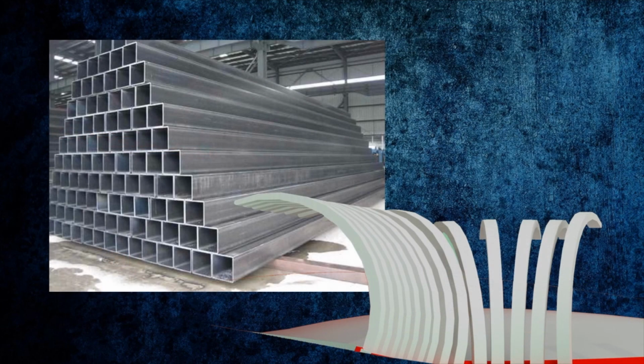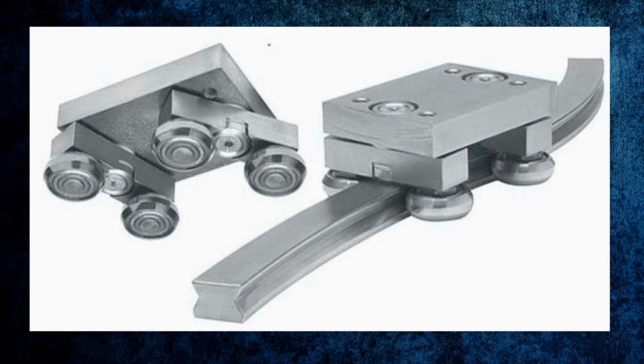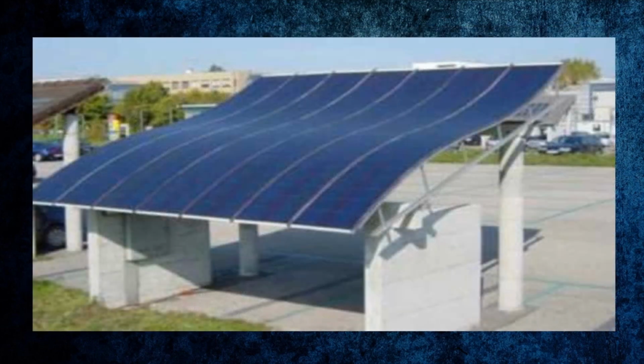The ribs are lightweight aluminum square tubes, 3mm thickness. The ribs move on a stainless self-adjusting steel railing that can move in a linear direction or a curved direction. There are 32 main ribs, each carrying flexible photovoltaic cells, 300mm width and 4.5 meters height. The electricity generated from the photovoltaic cells is used to charge the main battery through wire running under the railing.